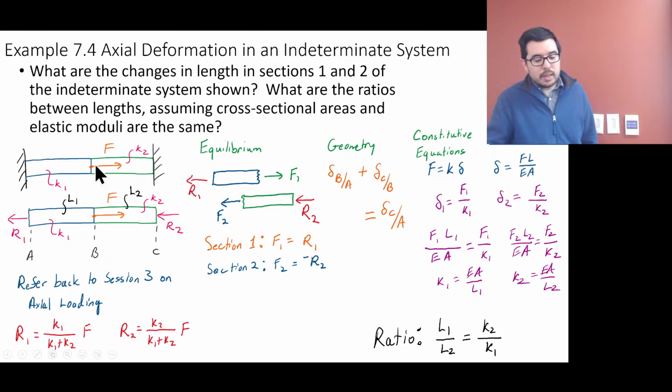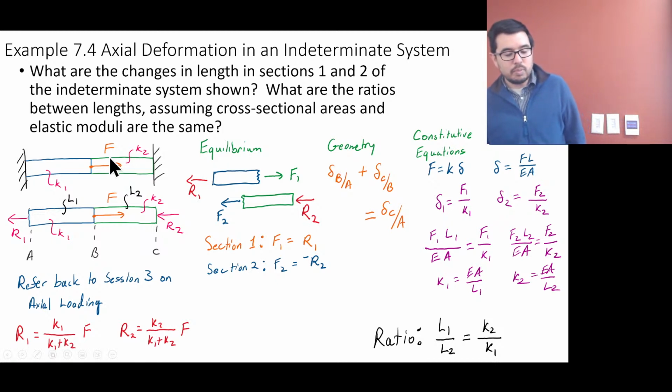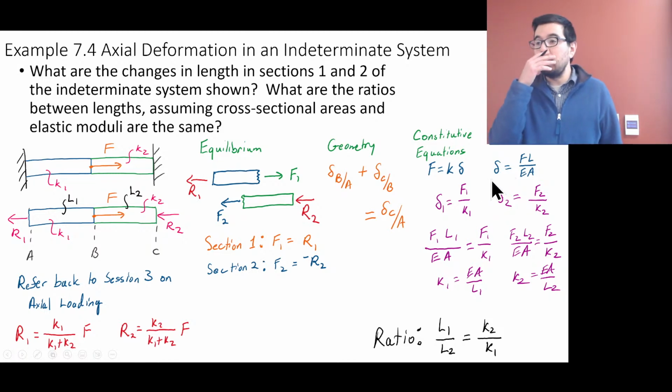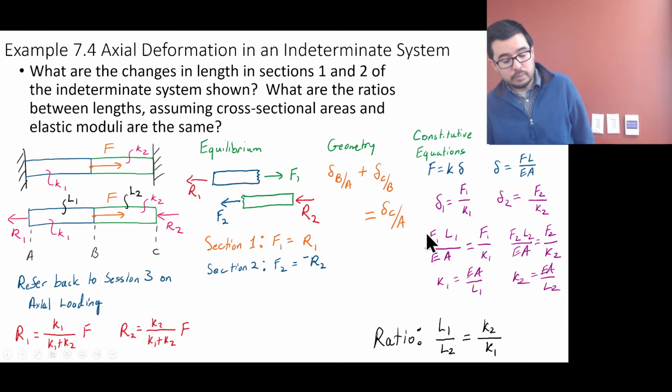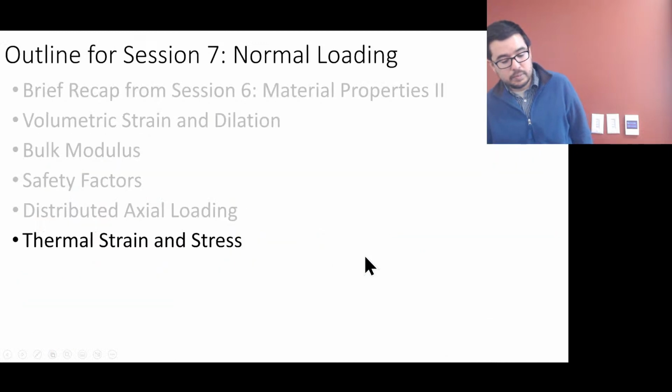But the point here is that we can begin to solve problems with axial deformation using our additional knowledge that we have in terms of delta being equal to the integral of PL over EA. Okay, final topic.